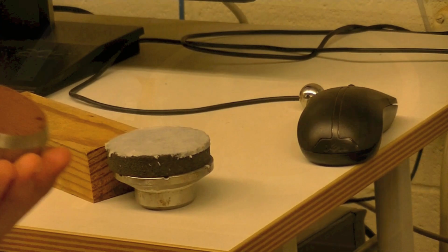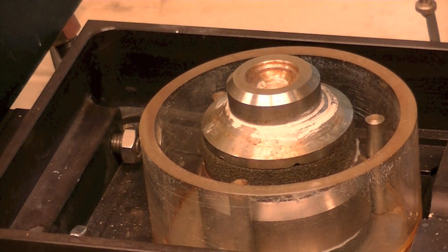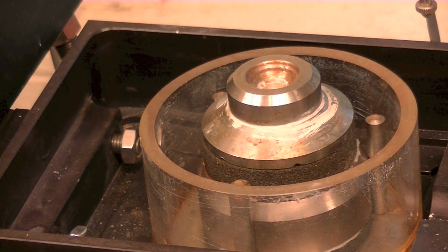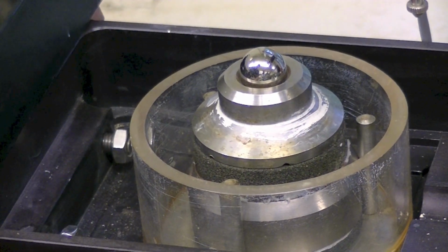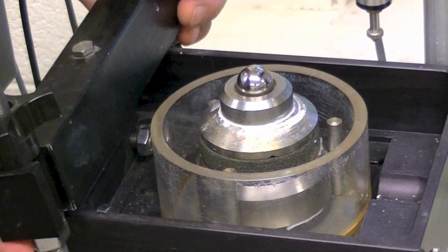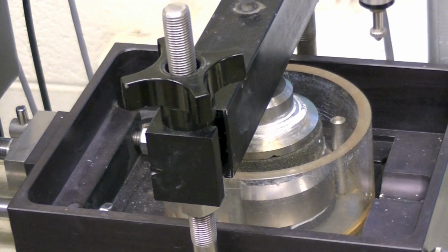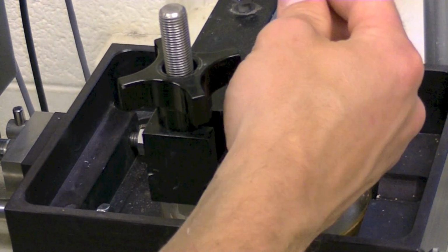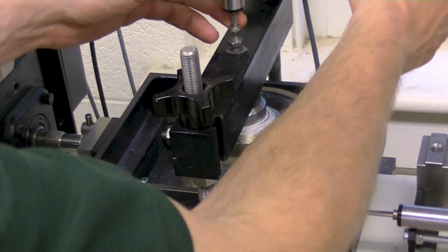Next, place the trim sample into the cup on top of the porous stone. Be sure the beveled edge is pointing in the upward direction. Place the filter paper, then the porous stone on top. Place the top platen and ball on top of the porous stone. Make sure everything is flush and will bear down evenly on the sample. Swing the load beam over and seat it on the ball. Tighten the wing nuts on both ends. Position the LVDT so its tip rests on the load beam.